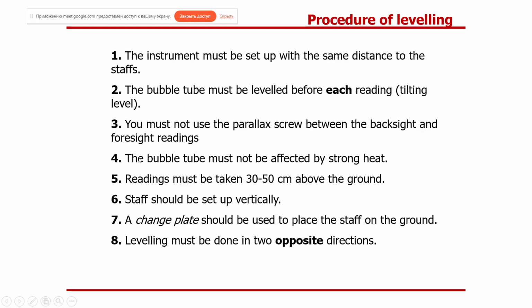So the bubble tube must not be affected by strong heat. Often we can use an umbrella to protect the instrument against the strong heat, against the sunlight.